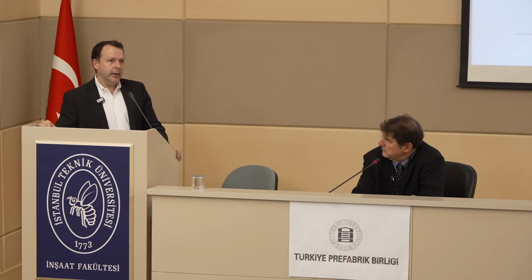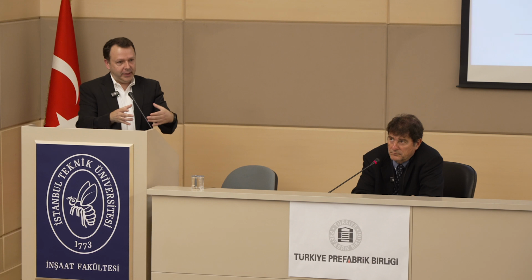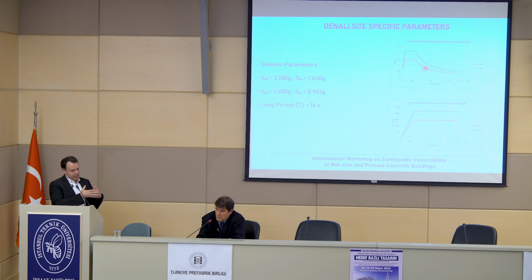On the second one, the goal is around 1%, right? And then as you're actually detailing it, it's going to be close. But having 1%, we know that we're going to have well-formed hinges, good ductility, and it's not a balanced design in the sense of moment curvature balance, but a balanced design in terms of a good design. So we try to hit very close to 1% in terms of the reinforcing steel ratio. All sides of the beams and columns to make some limited amount of reinforcement placement in the cross section.